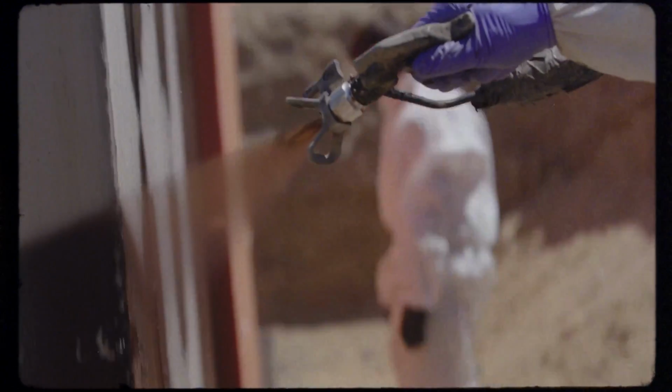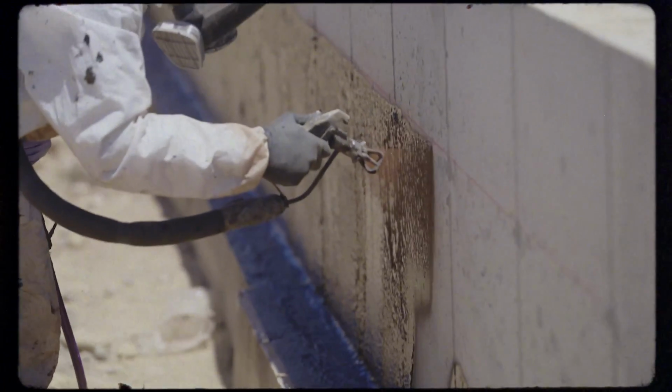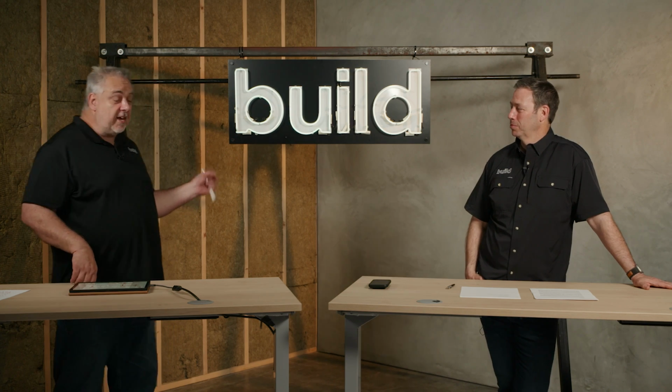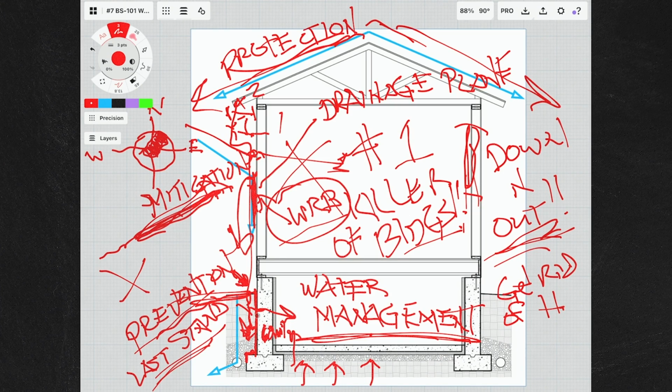What I mean by that is, it goes on nice and neat, but guess what happens right after it gets done? Some guy jumps in his excavator, he grabs that pile of dirt and rocks, and he swings it over and just dumps it freely. And so you get those rocks bashing at it. Yep. So I always call for a 60 mil waterproofing.